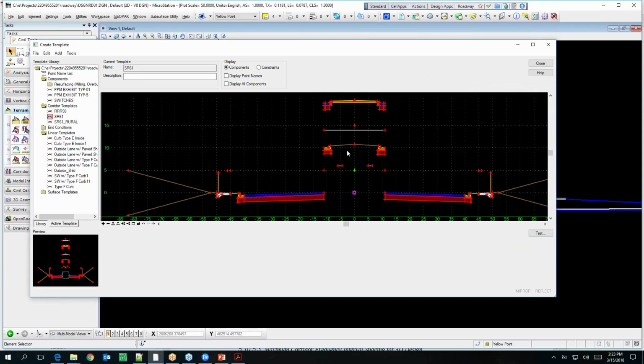redundant surfaces. Yep. So it would be my objective to just build the unique bottom surface underneath the sidewalk, underneath the pavement, underneath the curb. And if the curb is next to the pavement, then it would be one contiguous for curb and pavement. The sidewalks could be separate surfaces if you wanted. Otherwise you're going to have redundant surface lines, right? If you try to pick up the fills and the top of it, and then the utility strips and all that. But theoretically, the bottom is supposed to include cut and fill, yes? The bottom? Yes.